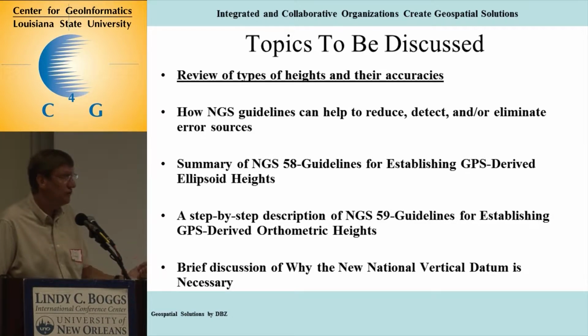Does that mean you're never going to have to level? No. You're still going to level. You're still going to need some very accurate relative differences over very short lines. So leveling's never going to go away, in my opinion. You're always going to need it. But you won't be running 50-kilometer level lines. There are still some states that are doing some of that. You got Florida, Minnesota, Wisconsin, and Mississippi just did some. So it's still necessary now.